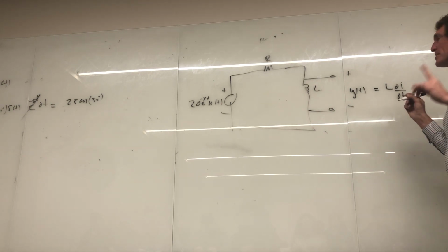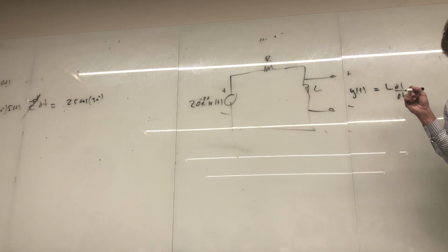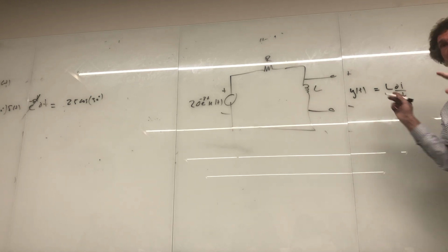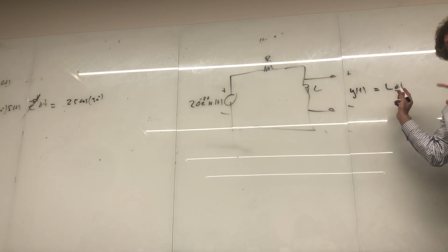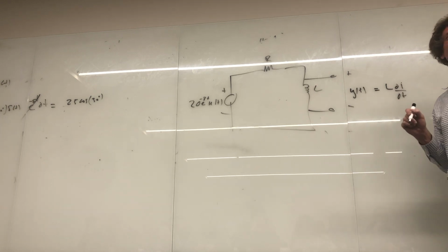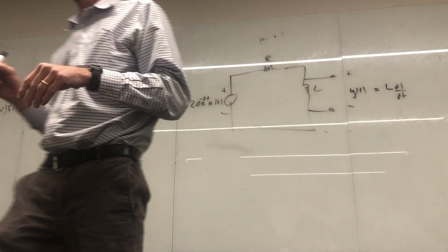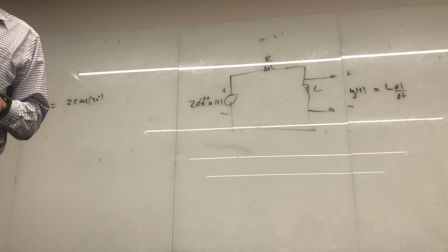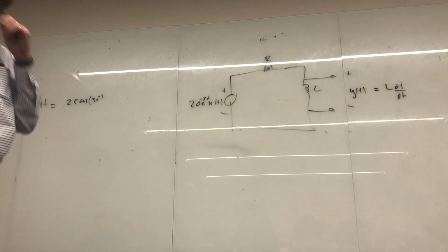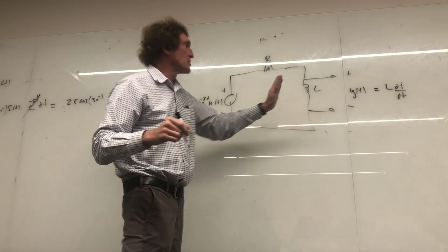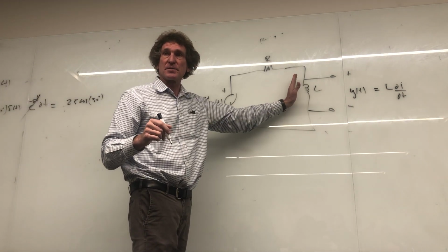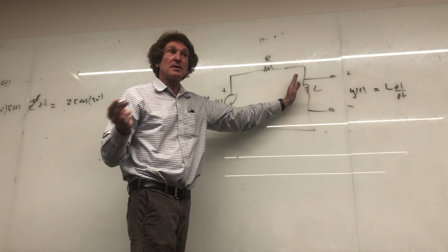I'm going to do this two ways. The first way is I'm going to take a look and actually solve for the current, then the voltage by taking a derivative. And the second way is to show you the trick with Laplace transform. Are there any initial conditions for the current in the inductor? Is it nothing? If there's not an initial condition stated, it's not assumed. Sometimes they'll put an initial current here at t equals 0, follow me? But if there's none, then you don't assume it.